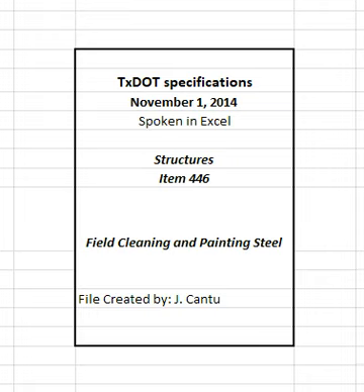Provide a concrete gray appearance coat, Federal Standard 595C, color 35630, unless otherwise shown on the plans. Use differing colors for each individual coat with enough contrast between colors to distinguish the various steps in the painting process, including differing the color of the stripe coat relative to the primer and intermediate coat. 2.1 Paint systems. Standard paint systems for painting new and existing steel include the following.